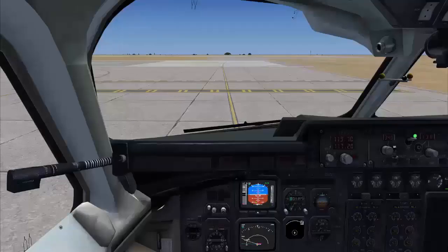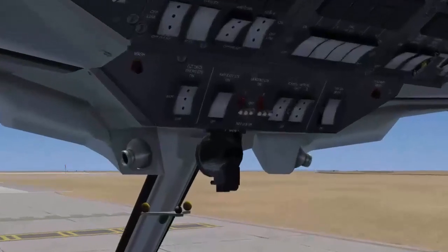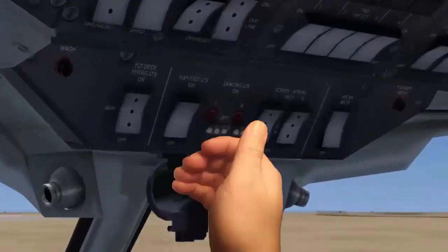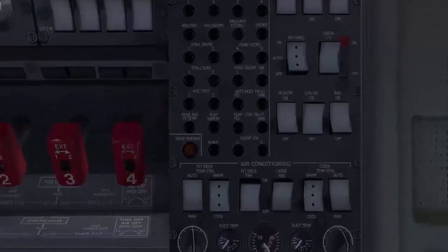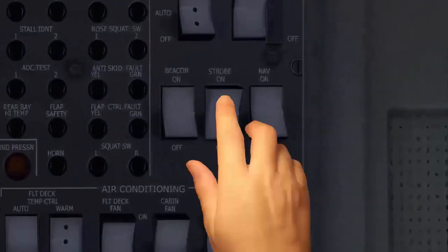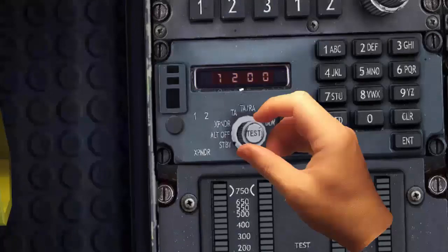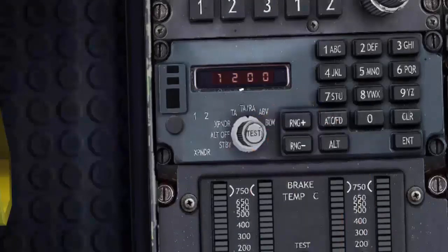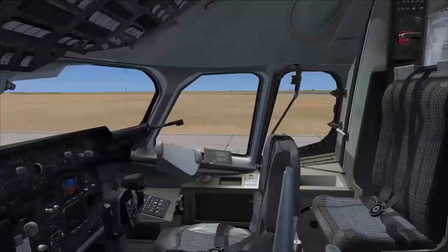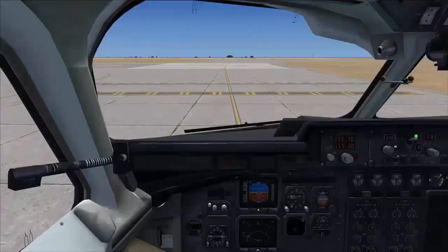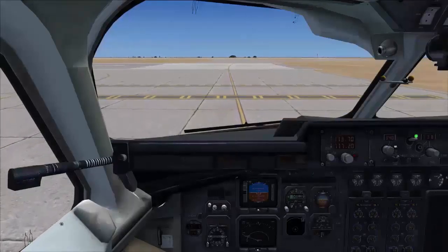When we receive the takeoff clearance from the tower, we do the runway entry or takeoff items, starting with the landing light. Select on. Strobe set to on. Transponder select TA/RA, traffic on final, clear. Advance thrust levers to allow the aircraft to move to the lineup position.